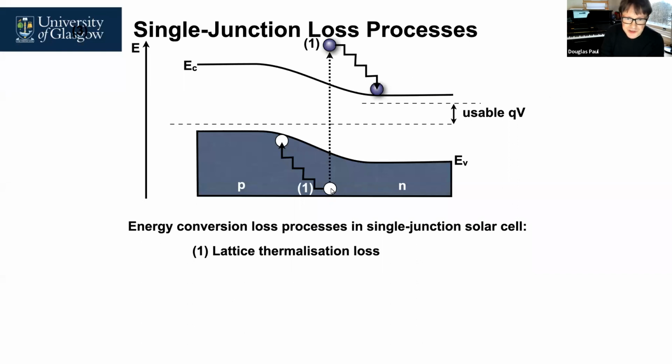For the hole, it's the same. Holes have got negative energy, the way this all works out. This is more simply to make it easy to use equations. A hole is a negative electron. So from that, it actually appears to go up in energy, but hole energies are reduced as you go up the page. So again, this is reducing in energy to get to the valence band edge.